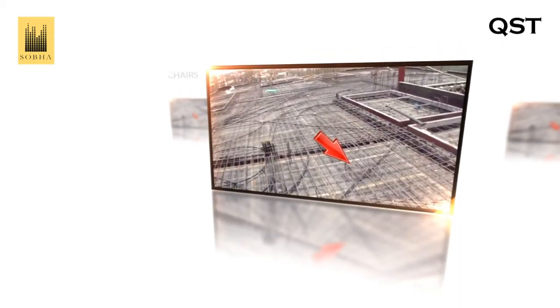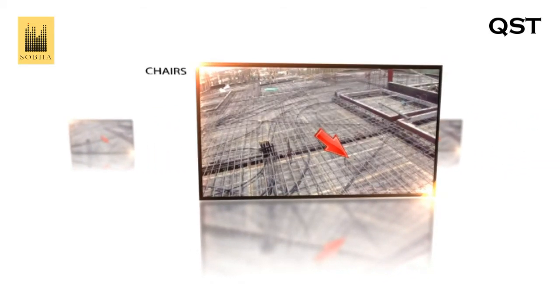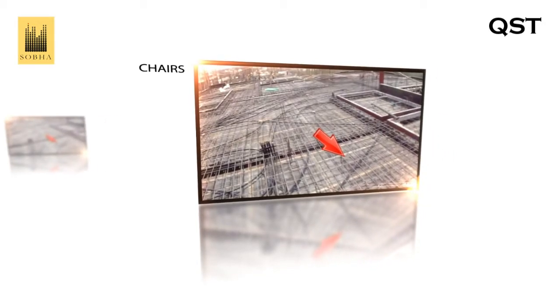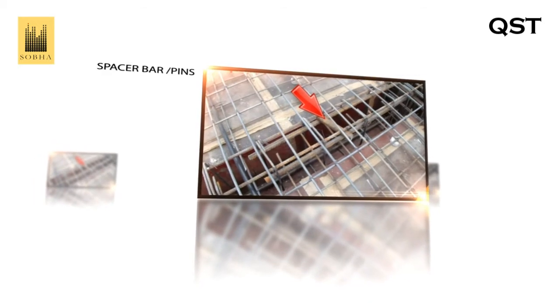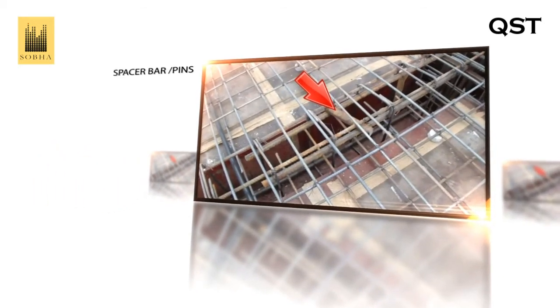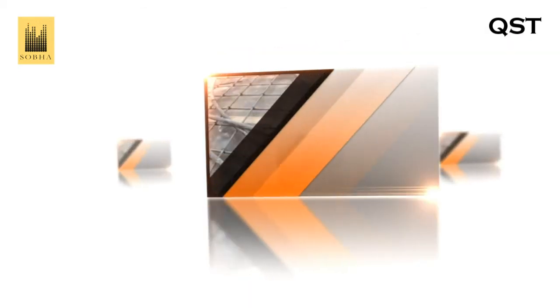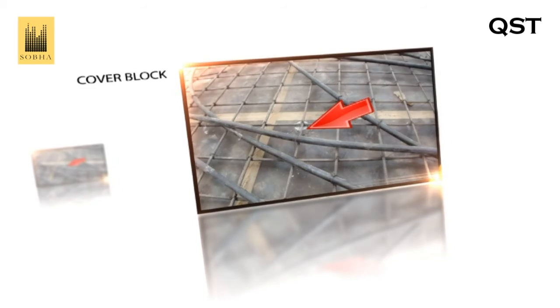Chairs. These are steel elements which separate the different layers of reinforcements for members like slabs and keep them in their respective positions while concreting. Spacer bars or pins. These are steel elements which separate the reinforcement and hold them in position. Cover block. This image shows the cover block placed in the slab.